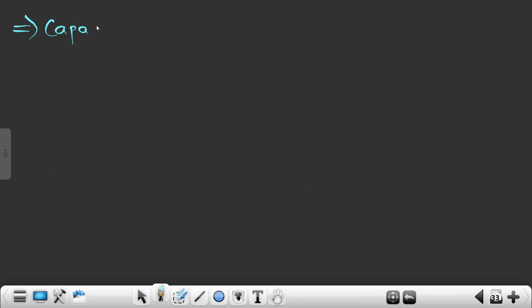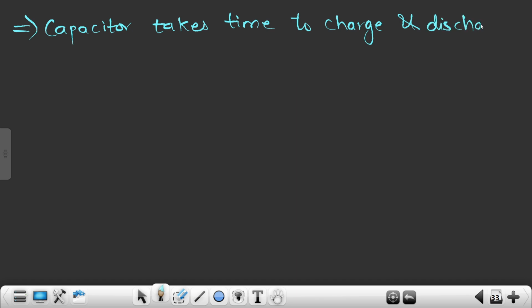And why exactly is this capacitive circuit present? It is present for internal compensation, to enhance the stability of an op-amp at higher frequency. I'm not going into that domain, but generally it is required to maintain the stability of an op-amp at the higher frequency of the signal.